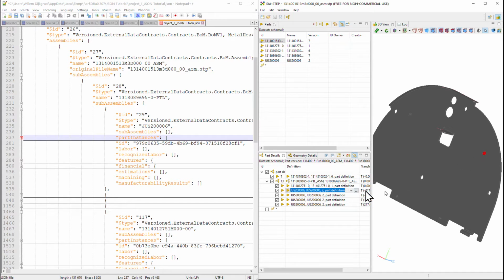A part instance is actually referring to that one definition, and then there exists a transformation, so it's kind of a clone which is transformed in 3D to have another position. For example, in this CAD system you see the transformation over here. So this refers to one definition of the geometry itself, and then it has 4 instances of that geometry, with each instance having its own transformation in 3D.